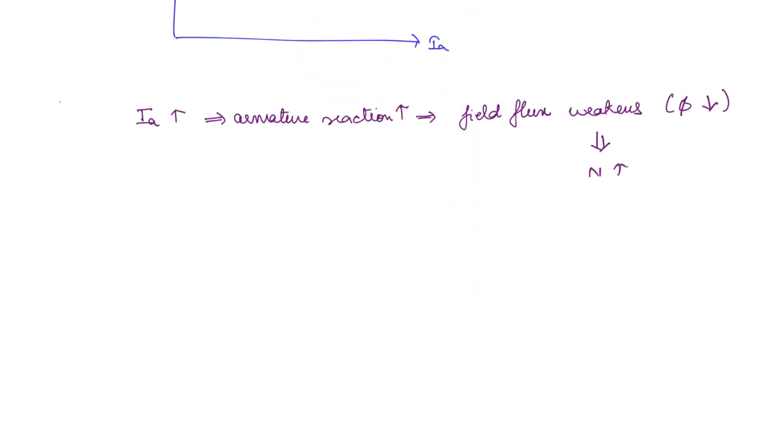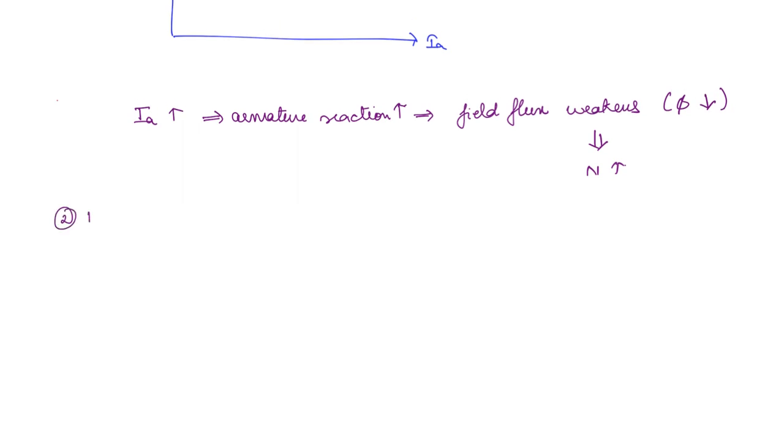Now next is torque versus current. Torque versus armature current, IA. Okay. So what is the relationship between the torque and armature current? T is equal to K phi into IA. So here we will take K dash to differentiate between the constant that we used for back EMF.